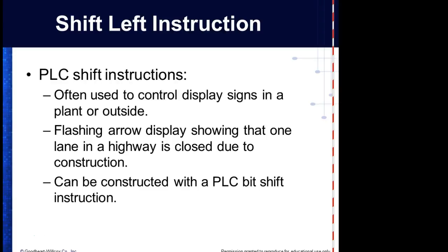So we had to write programs that divide, and that's what you would do. You would start taking your divisor and you'd shift it, and every time it would move into the carry bit, if it was a 1, you would subtract the divisor from the dividend. The quotient is the answer. Anyway, every time we saw a 1, we would subtract the divisor from it, and every time we had a 0, we would shift another one in. Does that make sense? It was really neat.